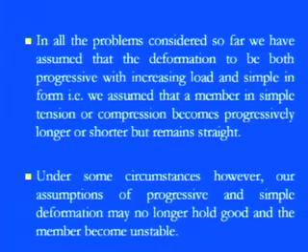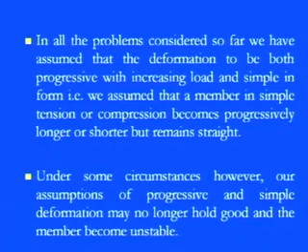So there are two things here. We are not considering any kind of nonlinearity, but we found that if a column or a strut is having buckling, there is geometric nonlinearity, there is material nonlinearity, and there are forces which are not exactly on the same axis, and due to that we have an eccentricity, and due to eccentricity we have buckling in that particular structure. So all these three terms are perfectly realistic. But we always assume simplified applications, and these are the simplified assumptions through which we are generally deriving the equations.